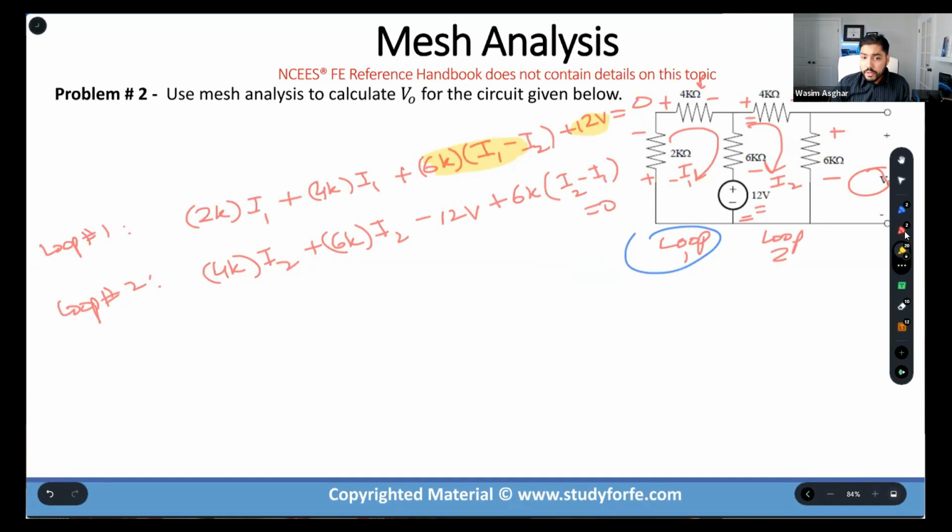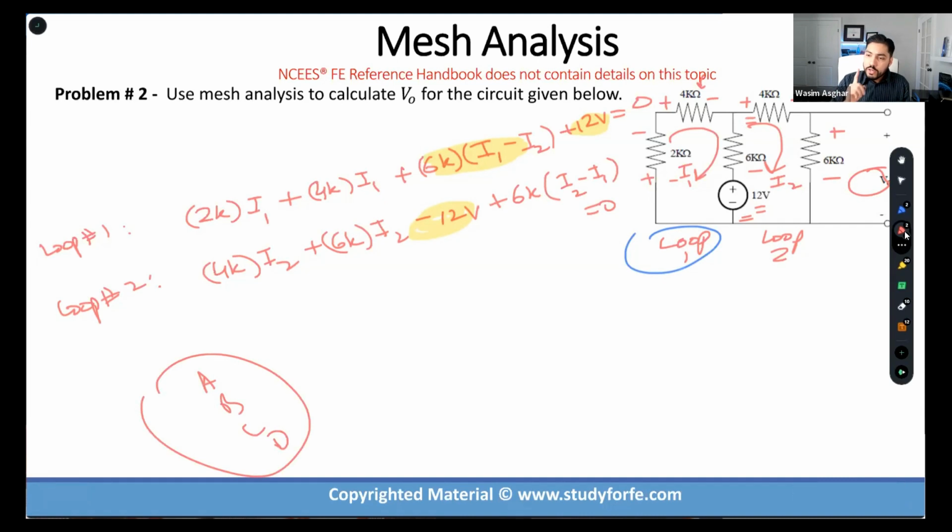So again, students can trip here. Some students can trip here. These are mines, landmines, okay? In these 2 steps, you have 4 possibilities of making mistakes. And then you walk out of the exam thinking you did well on circuits. And quite honestly, it's not difficult for an examiner, for me, right, to have options A, B, C, and D entertaining all 4 possible cases in which only one solution is right and the other solutions have actually taken you in different trajectories. So you do not assign positive and negative at the node where both currents meet, this is how you deal with it.